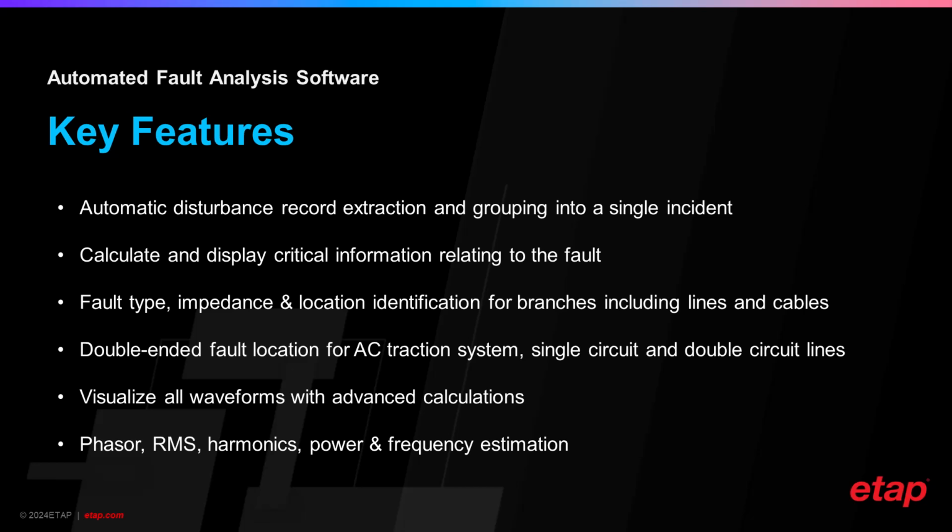It integrates with an advanced waveform viewer, enabling operators to see detailed representations of the electrical signals involved in a fault. This includes comprehensive calculations for phasors, RMS values, harmonics, sequence components, and more. AFAS supports reclosing events and differentiates between permanent and temporary faults. It records the sequence of operations at different levels, such as relay, bay, and substations, helping in understanding the sequence of events leading up to and following the faults.